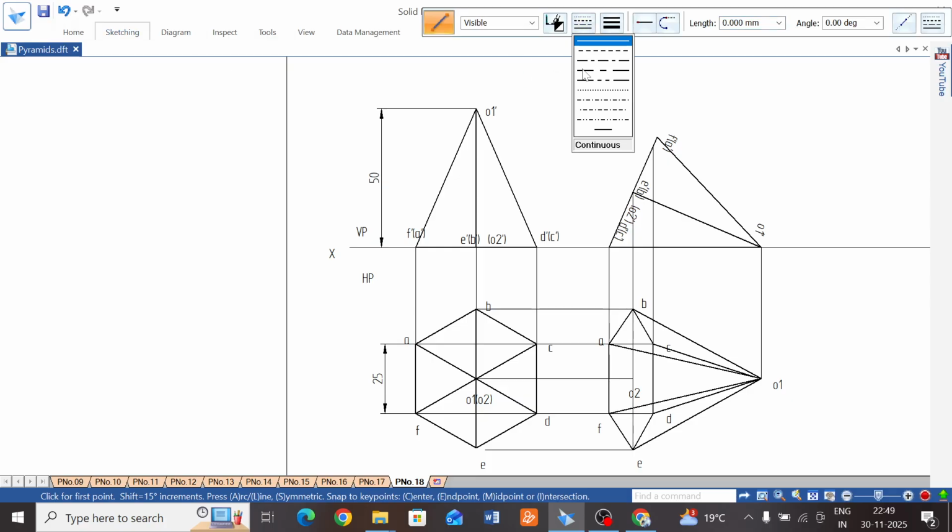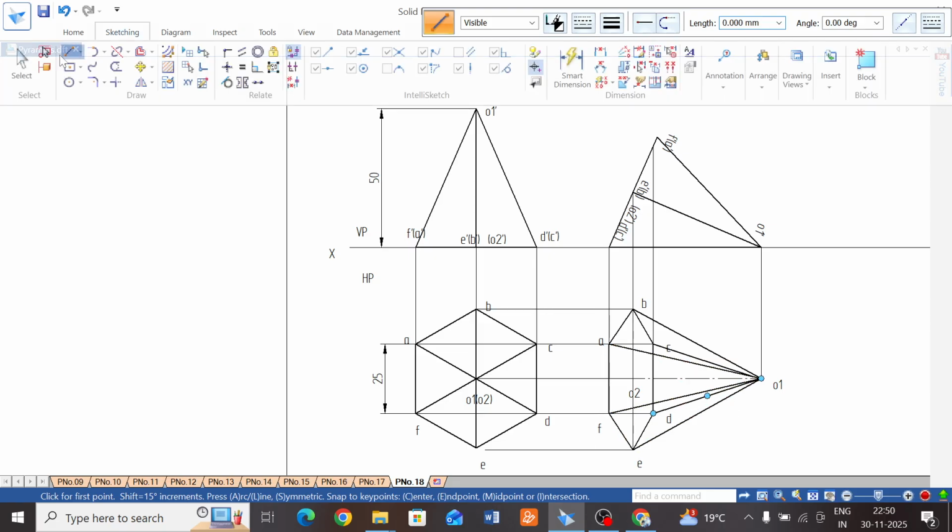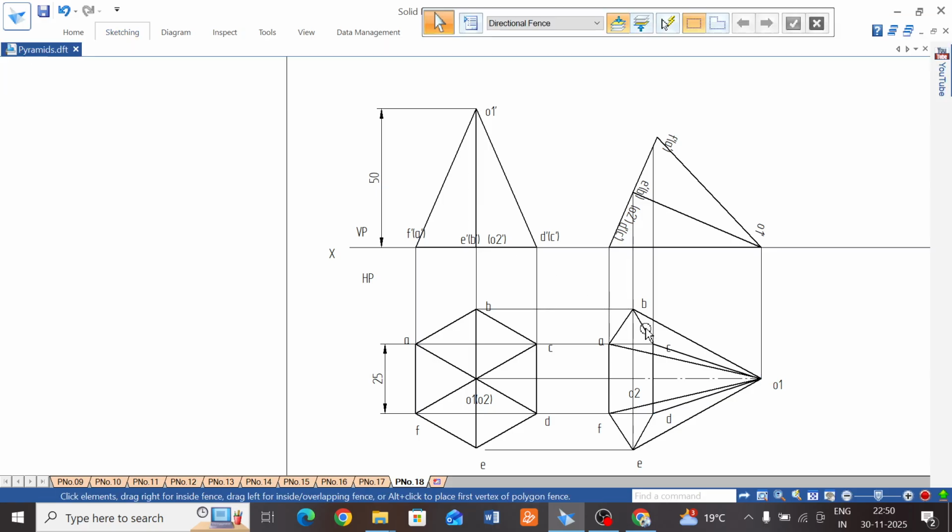Third one, axis with medium thick O2 to O1 and hidden line. Here you can see the line AB is passing inside, F is passing inside. Those two lines are crossing. Okay, this and this. See here it's crossing. Those two are hidden lines. You make it a hidden line. Okay, this is the second position, hidden line.